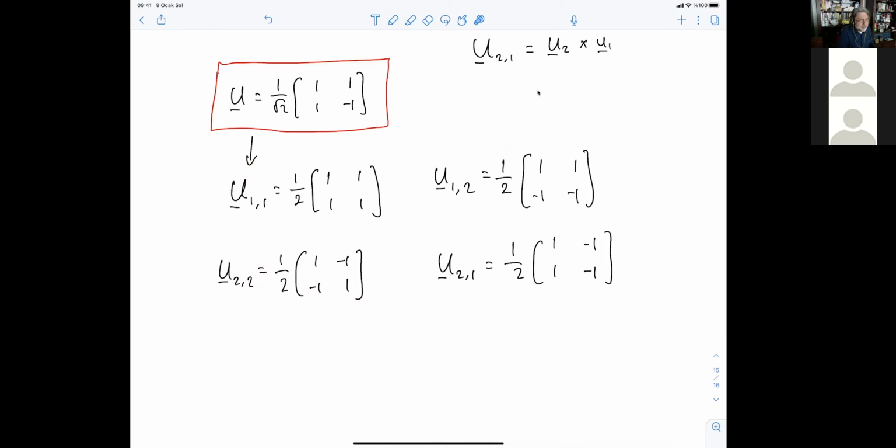For example, if you have an 8 by 8 discrete cosine transform, then it means you have 8 columns. By cross multiplying with each of them, you will have 8 times 8, 64 cross products. And that corresponds to 64 basis images.